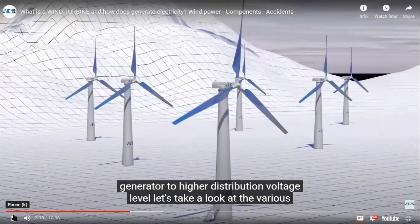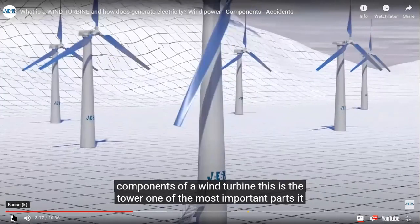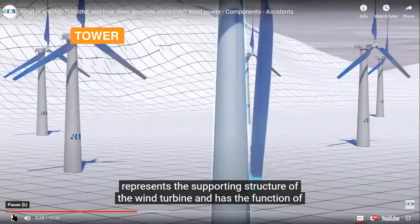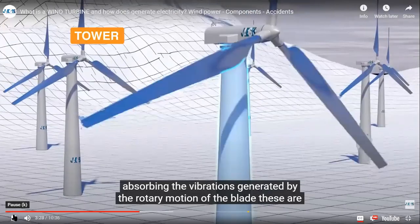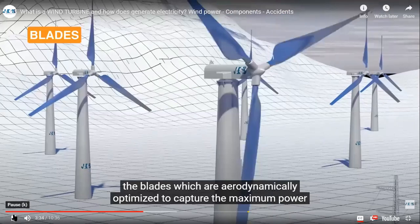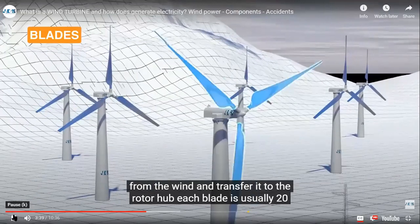Let's take a look at the various components of a wind turbine. This is the tower, one of the most important parts. It represents the supporting structure of the wind turbine and has the function of absorbing the vibrations generated by the rotary motion of the blade. These are the blades, which are aerodynamically optimized to capture the maximum power from the wind and transfer it to the rotor hub.